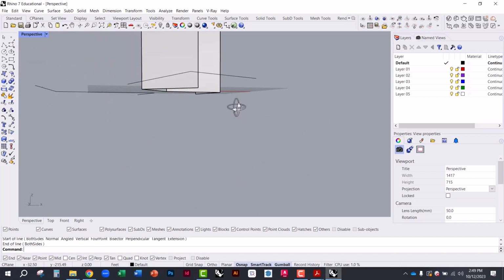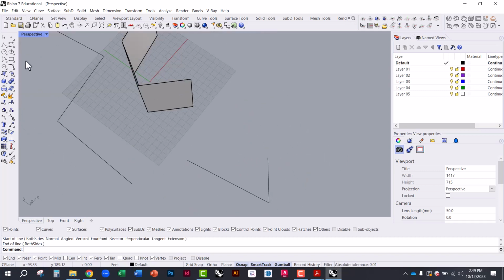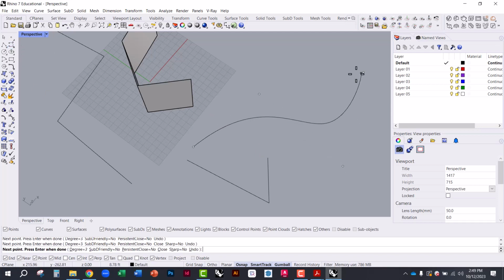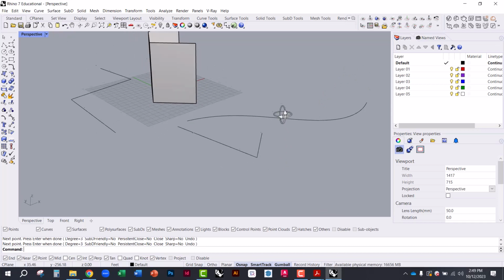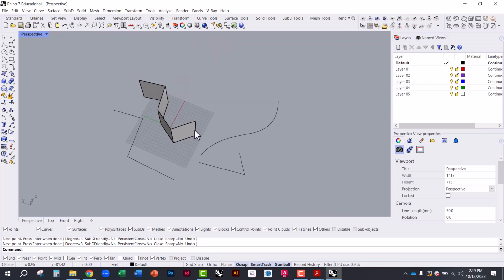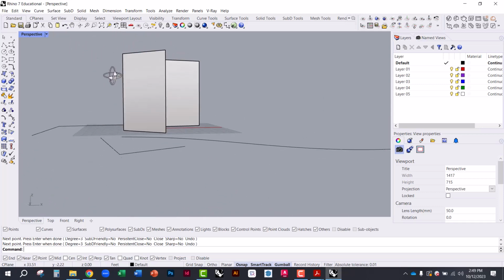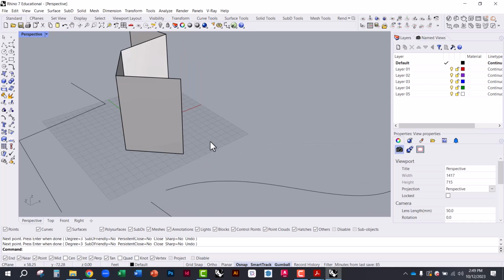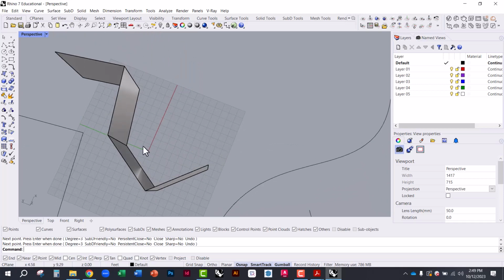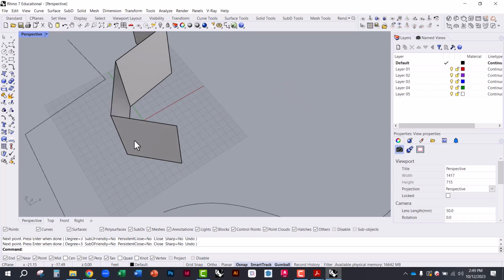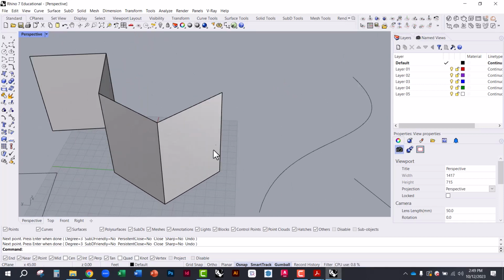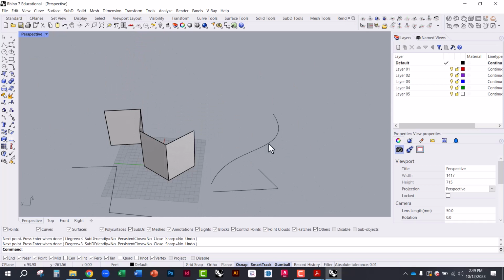And when you just draw lines or curves in Rhino, and I can show you a NURBS curve. This is a control curve. With this, when you draw this, it's flat. It's two-dimensional here. So with that, it's drawing it directly on the C-plane. So this is the C-plane, and this can be moved. This can be manipulated. That's why I like to have the C-plane tab up here, because if I ever want to kind of model something or draw something in space, I can change the orientation of that C-plane.